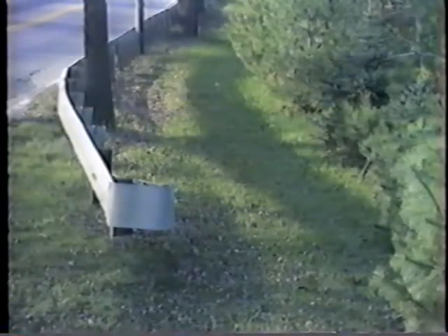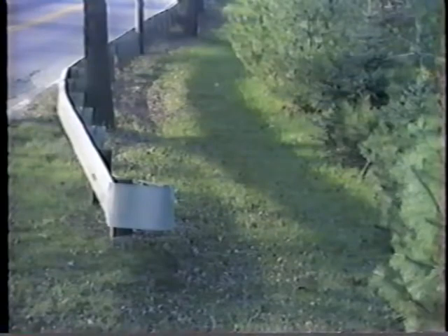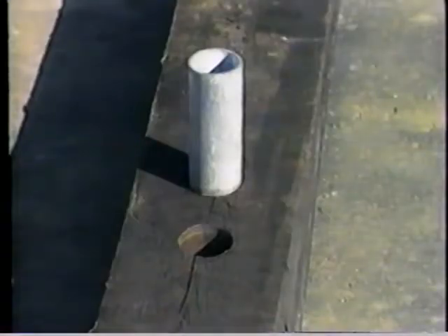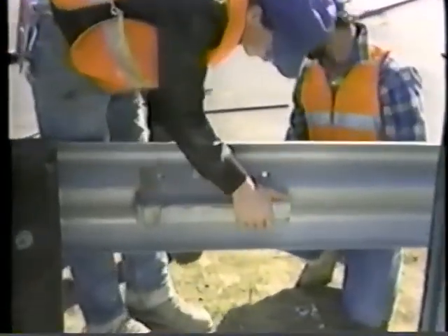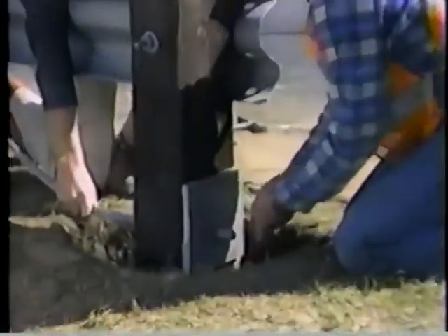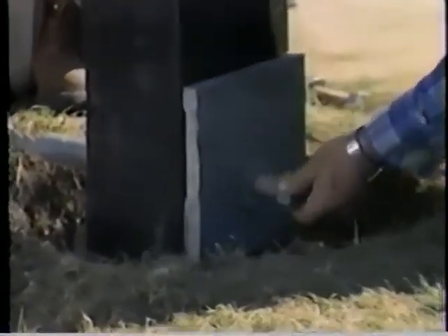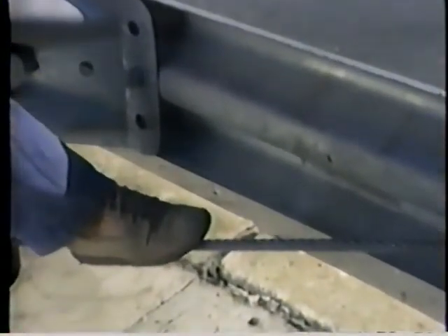Although no more than the first 37.5 feet of rail functions as part of the system, the flare must be maintained beyond this point if so designed. The first post of both the wood and steel post BCT systems should be drilled with a 2 3/8 inch hole. On wood post systems, the cable, attached by 8 bolts to the back of the W-beam section ahead of the second post, passes through the first post and attaches with a plate to the front of that first post. A steel insert is used through the drilled hole to keep the cable from tearing the wood post. The cable must be kept tight. 3/4 of an inch of deflection is acceptable.